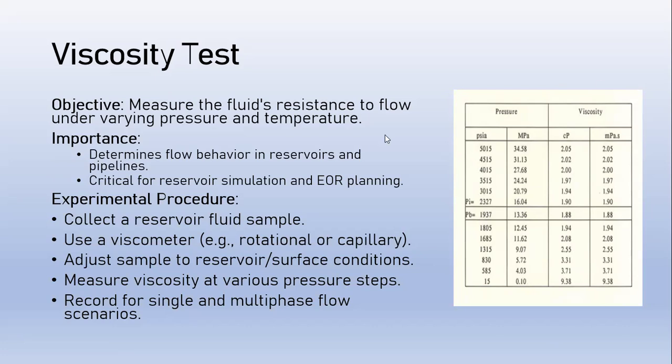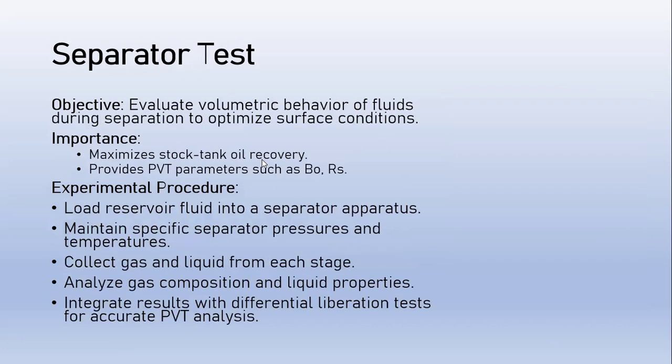Pressure against viscosity. And the separator test. The separator tests usually simulate surface separation into oil and gas phases to determine optimal surface conditions. It evaluates volumetric behavior of fluids during separation to optimize surface conditions. The main reason behind this is to maximize stock tank oil recovery. It also provides PVT parameters such as formation volume factor and solution gas oil ratio.